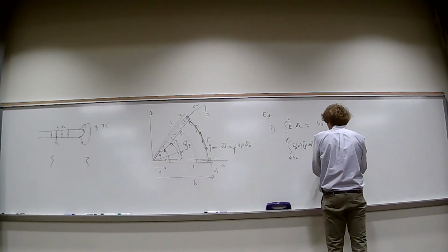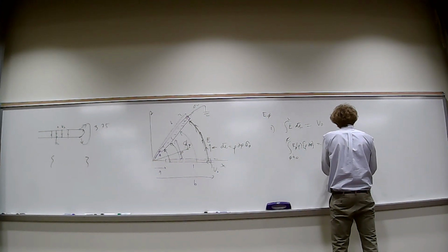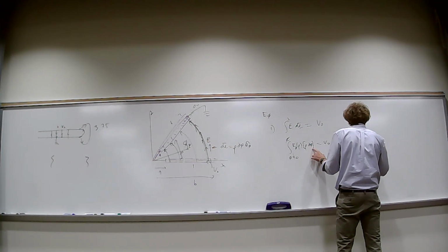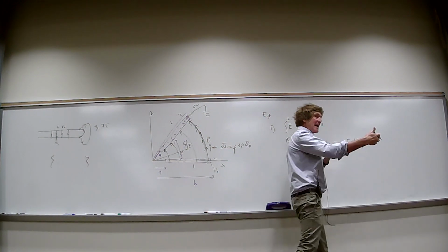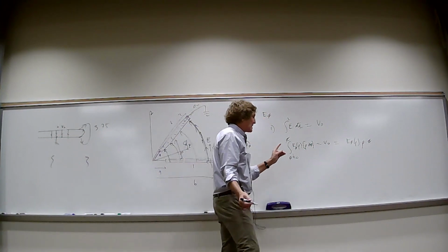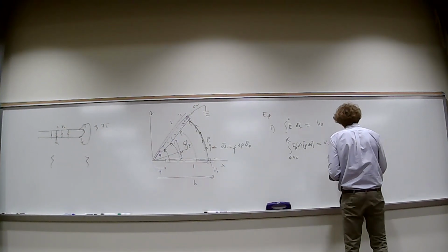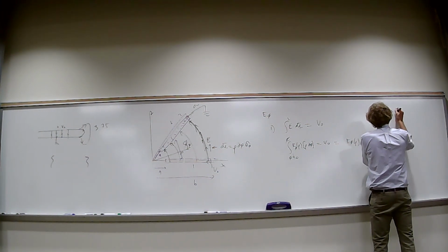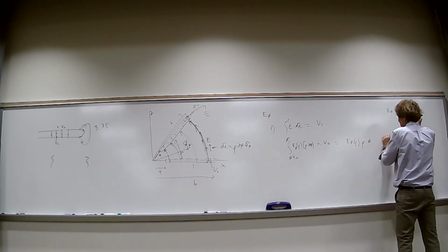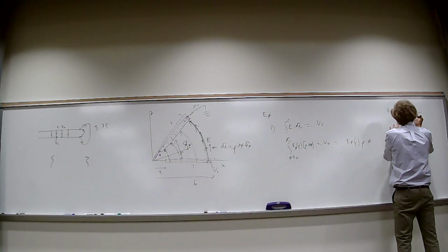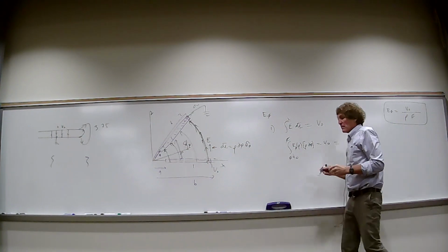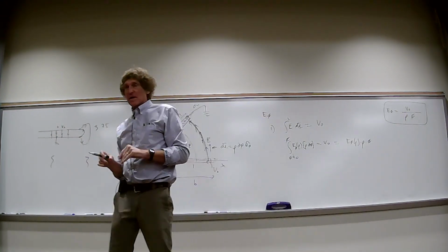So that means this right here, V naught, is equal to E in the phi direction as a function of rho. And then it's going to be times rho, and it's really times phi. And phi is nothing more than the angular difference between those two plates. Now, that means that E, I've got phi here. E of phi right here is equal to simply the voltage that was assumed, V naught, and then it's divided by rho and whatever the value of phi is. That's E phi.